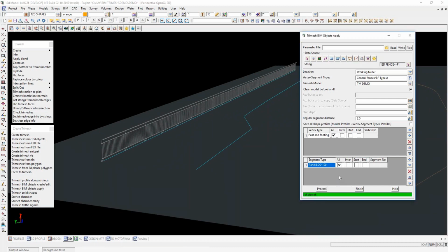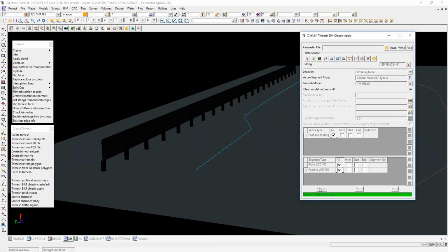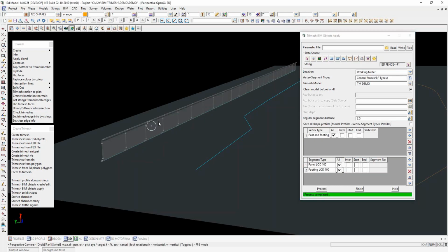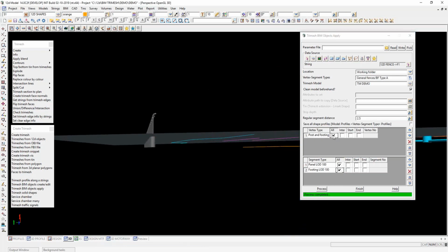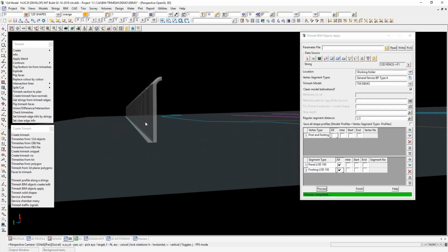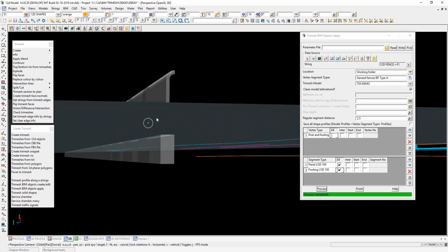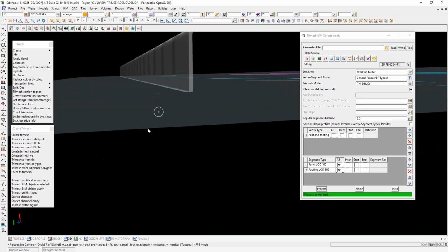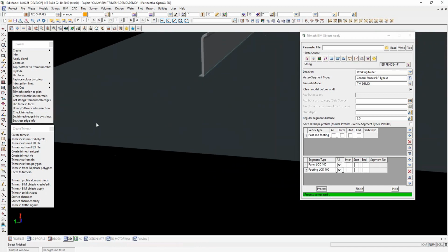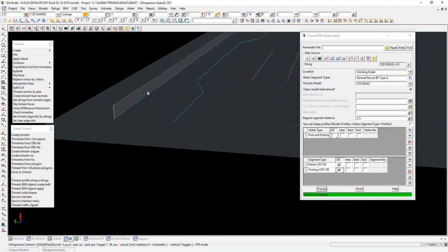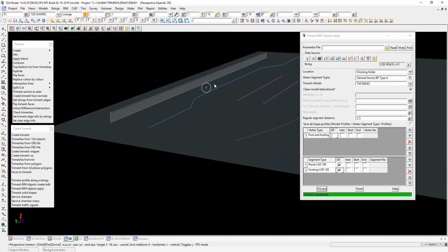Again, when you're looking at the level of detail part, you can get it to do that. This is where you can actually add the footing in. In the other one, I couldn't do that because I was only previewing it. Now I can turn around and put the footing in, and I just turn that one off. So now I've actually got just a see-through. It's a solid, but it's just got a blending on it. So now I can actually use that for clash detection and any side distance, that sort of thing I may want to do. So we have introduced those for that purpose.